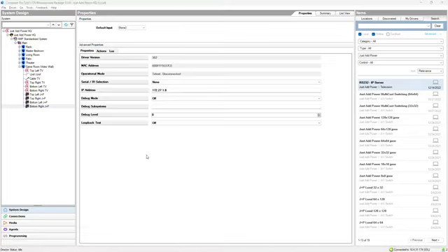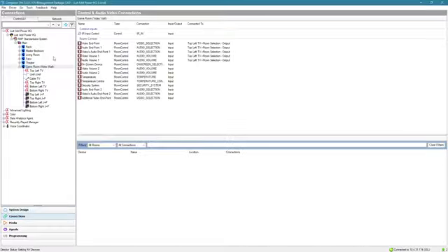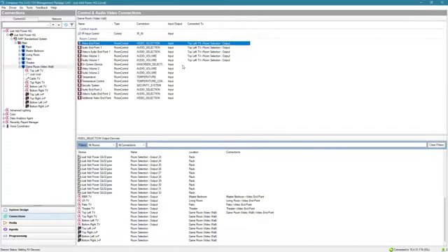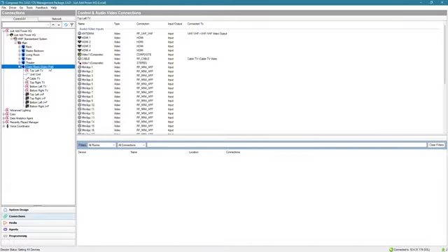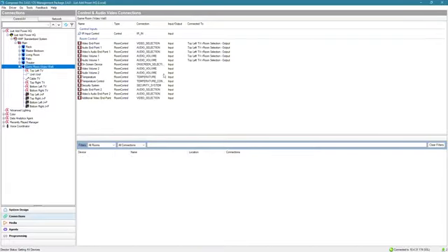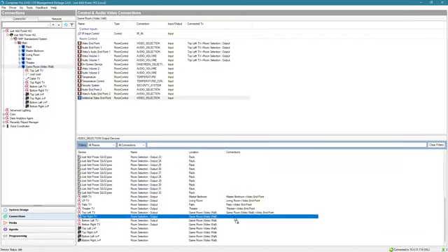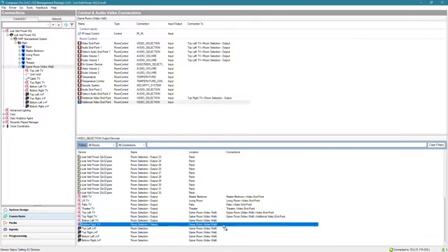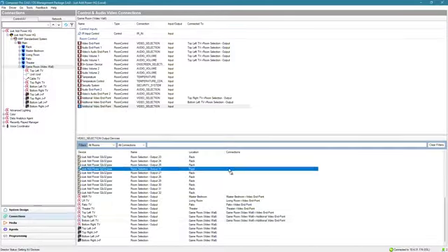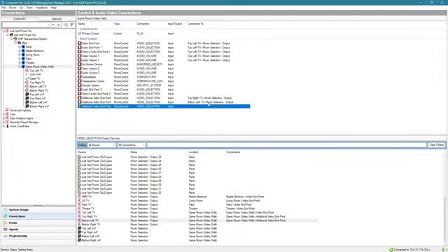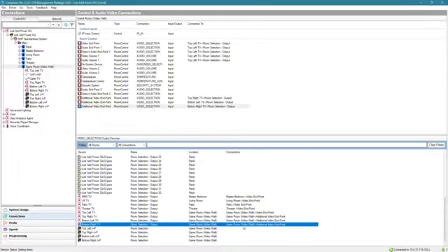Now, the reason they're all in one room is this is where the MultiDisplay manager comes into play. So if we select connections and we go to this game room, we'll see that the top left TV, or essentially the first driver we loaded, is our video endpoint for the room. But there are additional video endpoints in this room. So we're going to go down to all of the other TVs, and we're going to add additional video endpoints. Notice that we're connecting them to the TV drivers, not to the Just Add Power drivers at this point, because the control is of the TV for power on and off, and this is important for being able to manage power for these. So you need to add the TV drivers.